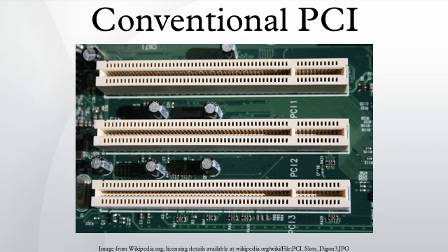Card voltage and keying. Typical PCI cards have either one or two key notches, depending on their signaling voltage. Cards requiring 3.3 volts have a notch 56.21 mm from the card backplate. Those requiring 5 volts have a notch 104.47 mm from the backplate. Universal cards accepting either voltage have both key notches.